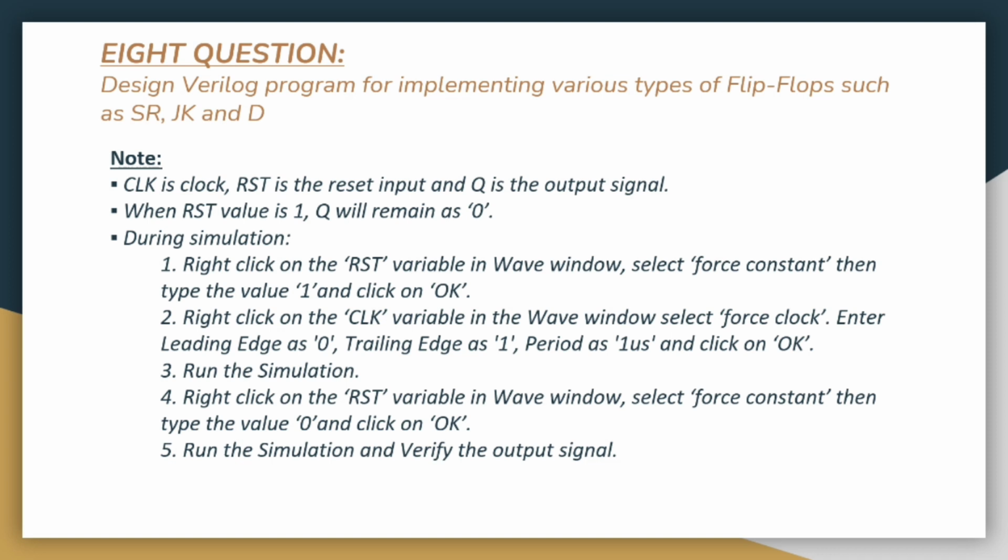Similarly, in the D flip-flop, there will be a single input. The D flip-flop is a better alternative that is popular in digital electronics. They are commonly used for counters, shift registers and input synchronization. In D flip-flops, the output can only be changed at the clock edge, and if the input changes at other times, the output will be unaffected.